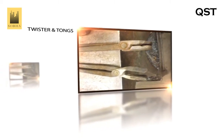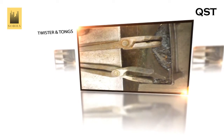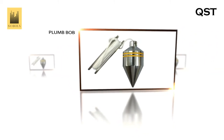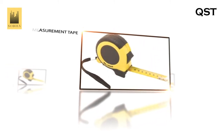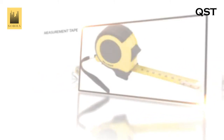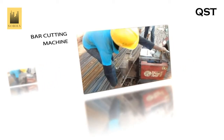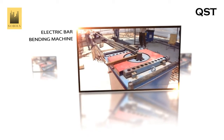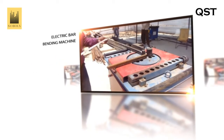Twisters and tongs are used for straightening or bending the steel bars. Plumb bob are used to check verticality. Measurement tape are used to measure any distances. Bolt cutter and the electric bar cutting machine are used to cut the steel reinforcement bars. Bar bending table and the electric bar bending machine are used for bar bending.